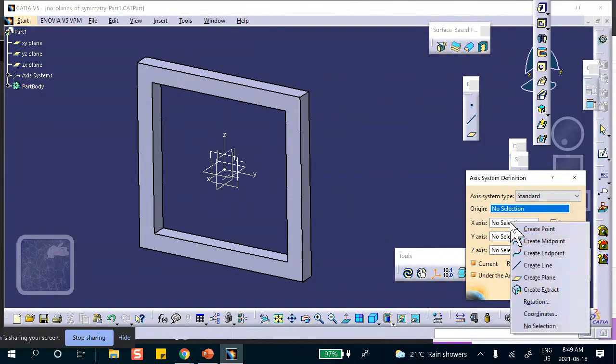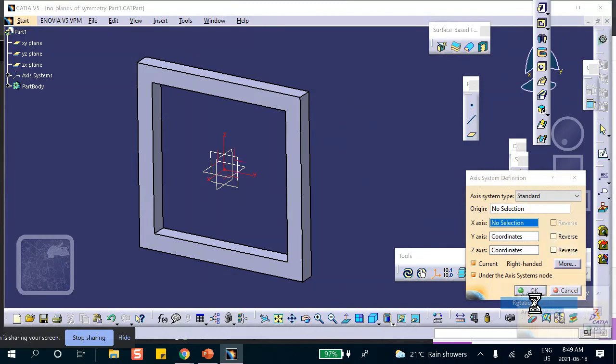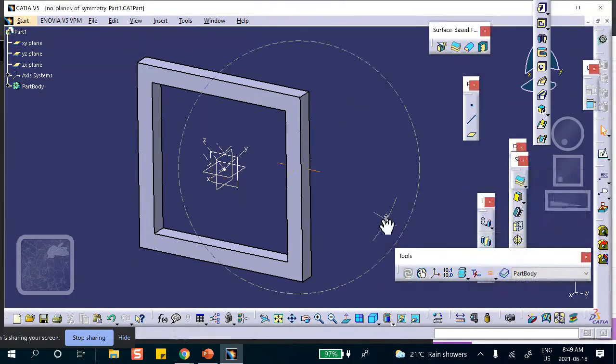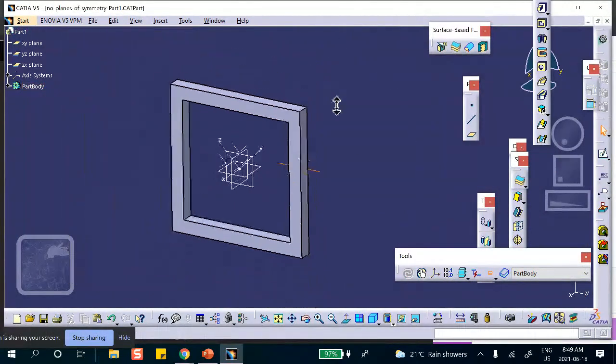So I'm going to rotate, put the cursor there, rotate the x-axis by 45 degrees. And watch what happens to that red thingy in the middle. It turns, and now it's at 45 degrees. So when I say apply a load in the direction y, it's actually going to be direction at 45 degrees. Okay, good. So we made that thing.